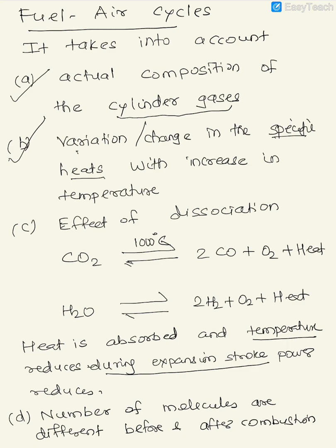There is a phenomenon which is called dissociation, which is just the opposite of the combustion phenomenon. In combustion, the products of combustion are formed and heat is rejected. It is an exothermic reaction. When the heat is released during this exothermic reaction, the temperature also increases in the cylinder, and at those high temperatures, sometimes the products of combustion dissociate.